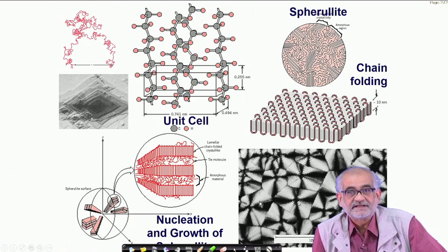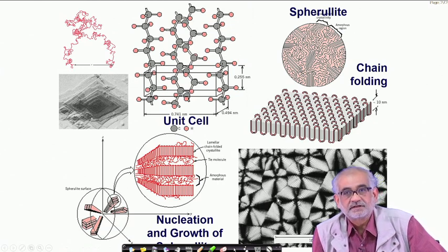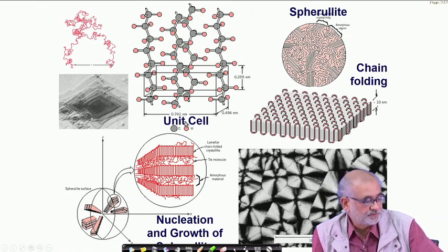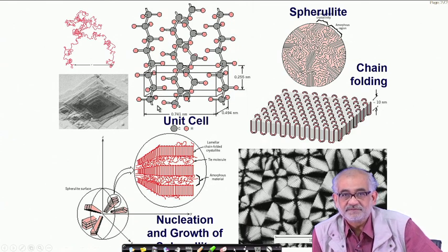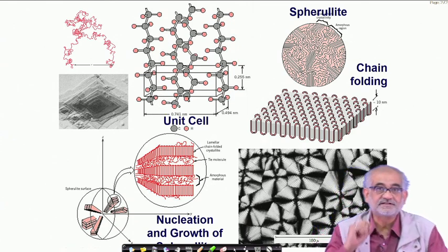But polymeric crystals are rarely 100% crystalline compared to their inorganic counterparts. This crystallinity essentially comes from the layers that are formed. If we imagine that this is a long chain, and we allow this chain to go through a back and forth, chain-folding motion, then from point to point there could be certain repetition of the species. And if you look from outside, you may see that certain types of atoms or molecules are being repeated at some regular distance in a given direction.